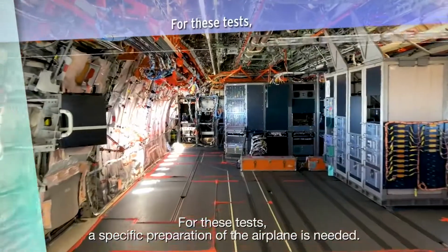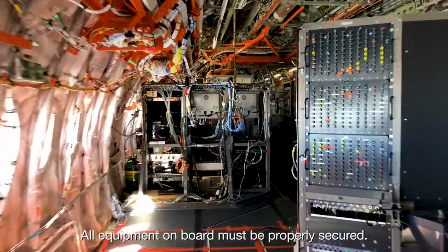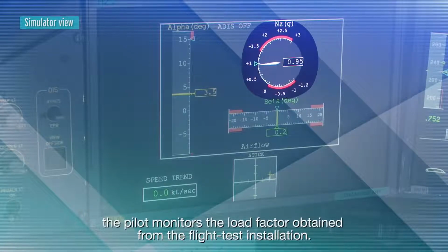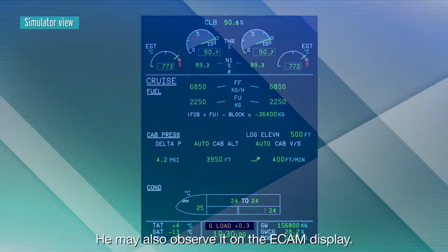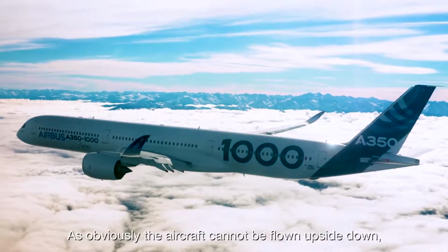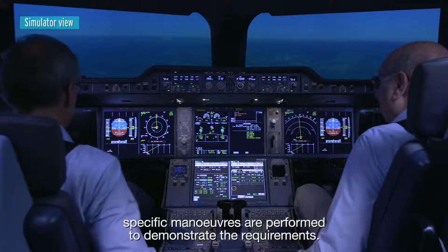For these tests, a specific preparation of the airplane is needed. All equipment on board must be properly secured. On a specific display, the pilot monitors the load factor obtained from the flight test installation. He may also observe it on the ECAM display. As obviously the aircraft cannot be flown upside down, specific maneuvers are performed to demonstrate the requirements.